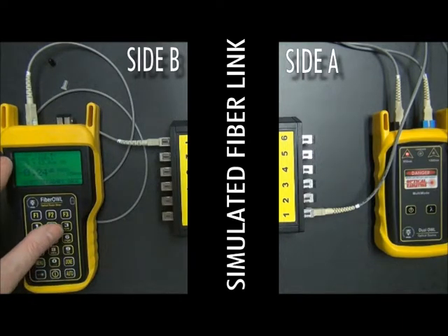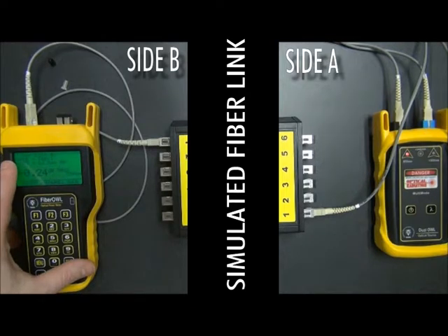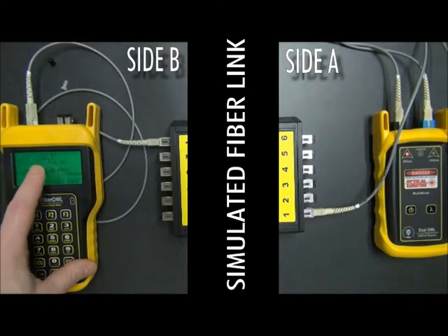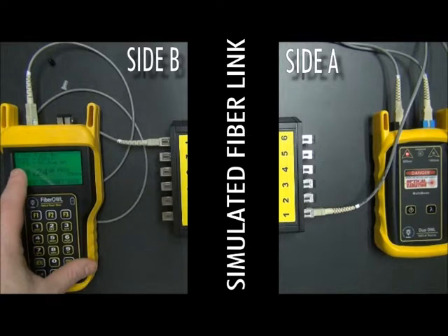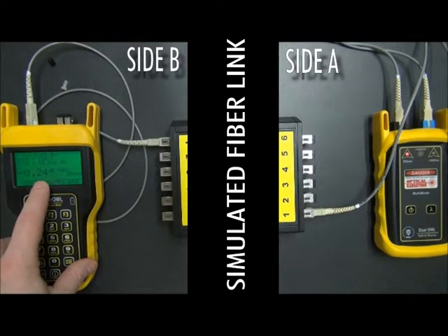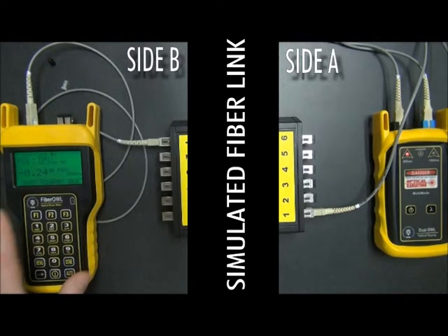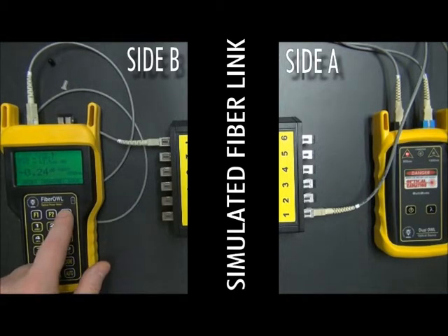And as you can see, all the information about our reading is here. So our fiber link ID, our fiber number, so fiber FBR:1 for port number 1, our fiber type, our loss reading, our pass reading, and our wavelength. So once we've got this information on the screen, we're happy with the result, we simply press F3 for save.